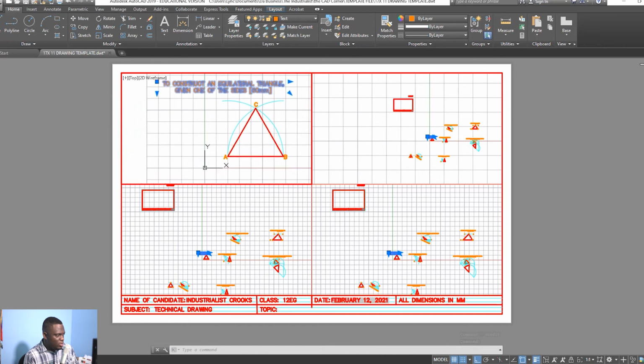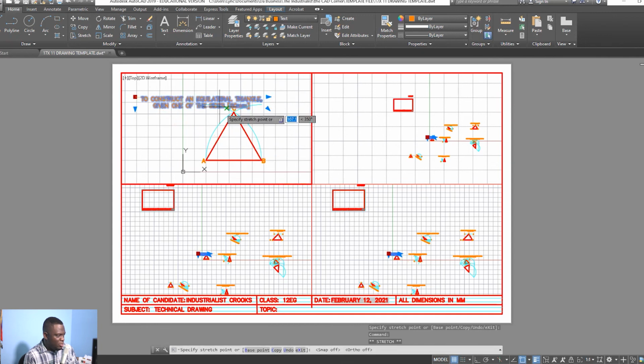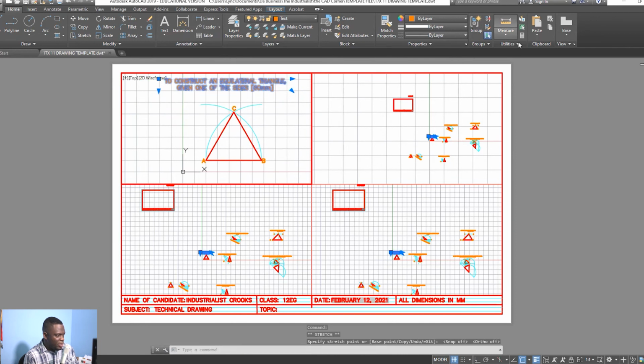I'm going to drag over, pan over a little bit, and move this so that it's like here. It's snapping to the grid. So let me turn off snap to grid. I'm going to turn off ortho also so I can move it sort of freeform, and I want it roughly about here. Right, I press escape.